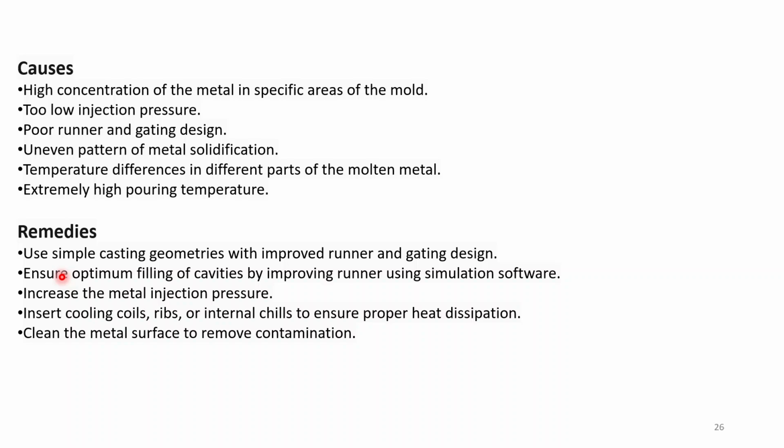Ensure optimum filling of casting cavities by improving runner using simulation software. So you can provide the diameters of the runner, riser, all these ingates and all. So that may also lead to improvement in the pressure of the gating design. Increase the metal injection pressure. So this pressure can also improve by using some tools as well.